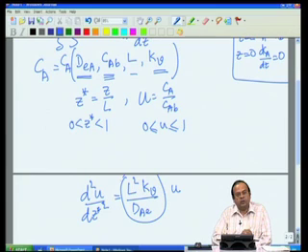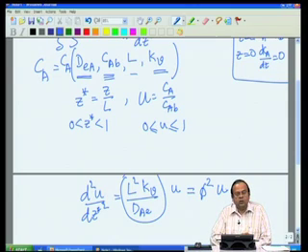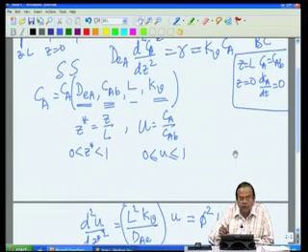and indeed it is a dimensionless quantity, and we call this the Thiele modulus phi, and it is represented as phi square, where Thiele modulus phi square is defined as L square kV by dAe. Now, what is the advantage now? So, our equation is now in a dimensionless form, but more than that, if you look at this equation, which we actually derived from this mass balance.